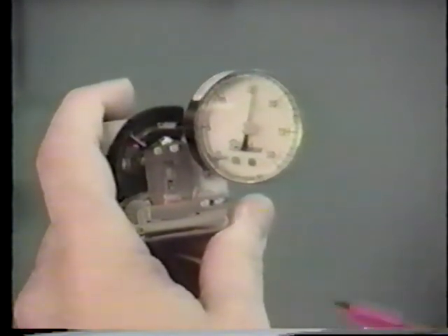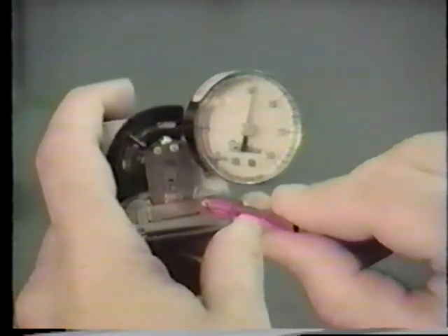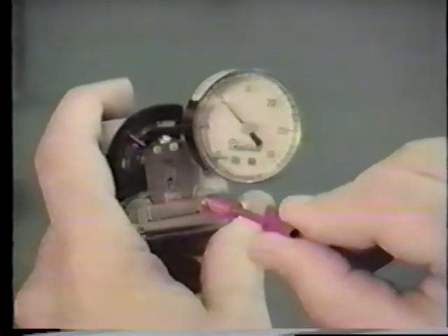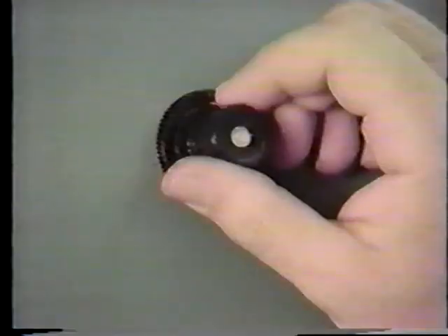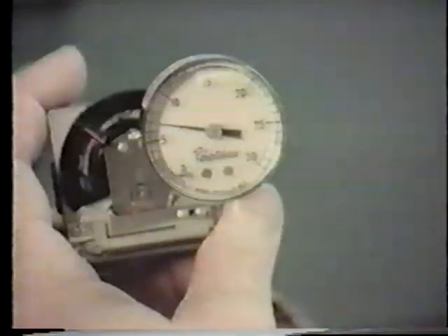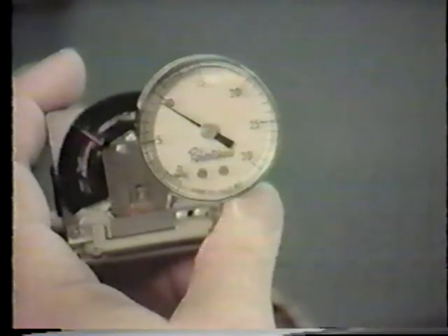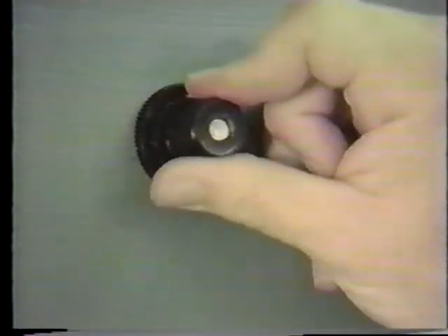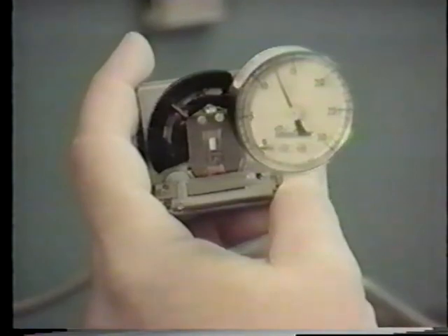To lower the switchover point, use the calibration wrench to turn the switching screw, located on the lower right of the thermostat, clockwise 1/8 turn at a time until the branch line pressure falls. The next step is to lower the main air pressure to the desired system day cycle pressure and observe the branch line pressure. The branch line pressure should rise to the main air pressure. Next, raise the main air pressure to the night cycle setting and observe the action of the thermostat for proper function.